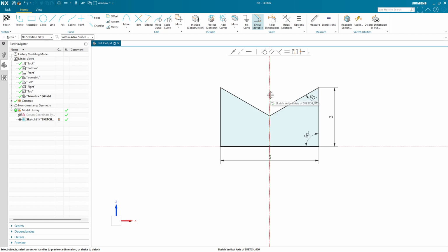If you don't believe me, do the trig. I promise you that's how this works, because we have equal length hypotenuses and equal length uprights on these triangles. So we have a part that's symmetric about this green center line. Everything is constrained. There is no geometric ambiguity in this anymore, and we've achieved a fully defined part.